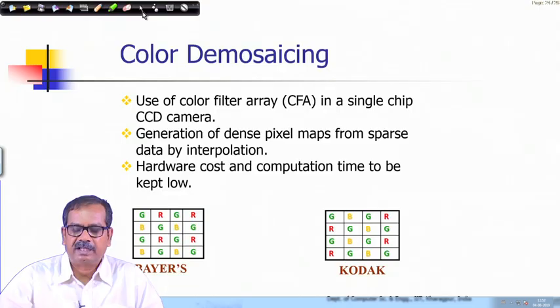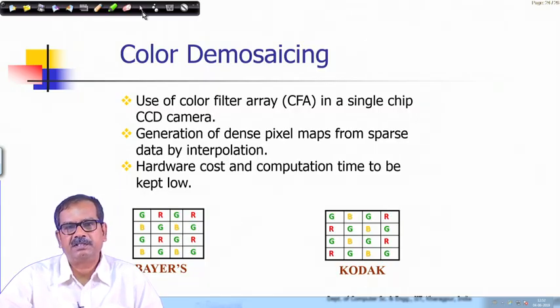And as the motivation, technologically it is simpler to design and manufacture this kind of camera, because spectral coherency of the reception is not required here. You can simply use color filters with certain patterns in front of your lens, and each pixel will receive only energy in that spectral band.